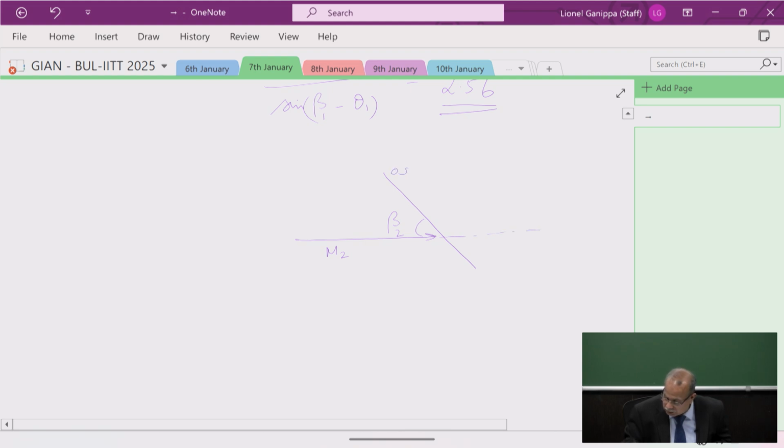The flow encountering the oblique shock will turn by an angle theta. What is this angle theta? The same angle through which it has already turned. What's that angle? 20 degrees. So again, M2 which you already calculated is 2.56, and theta 2 is the same as 20 degrees. What is the value for beta 2?